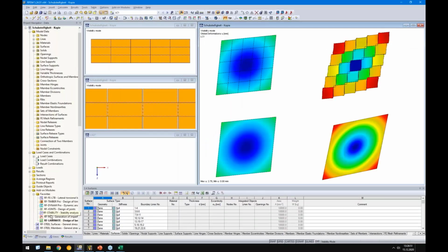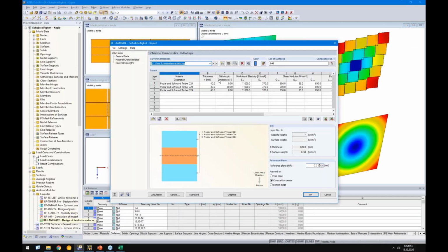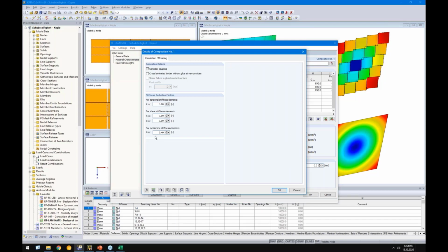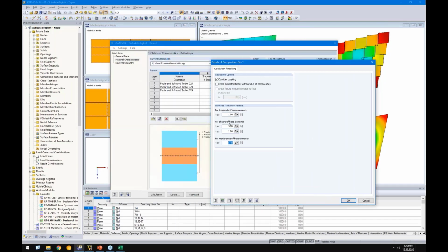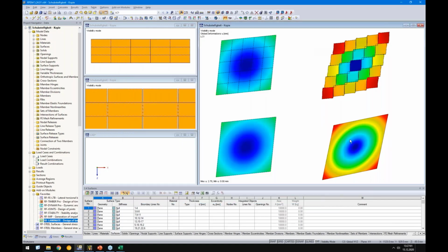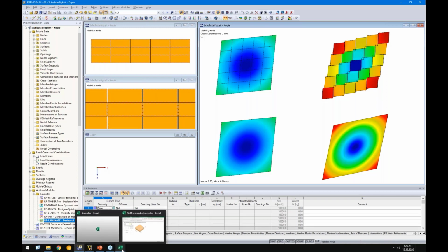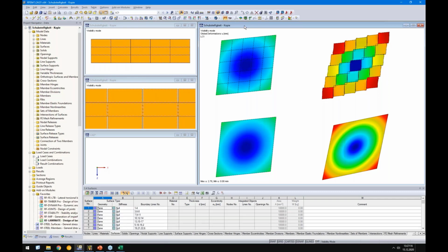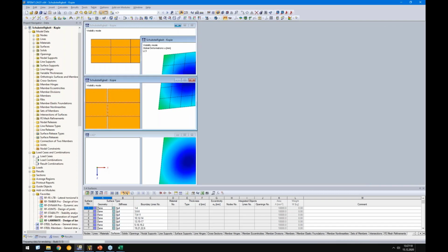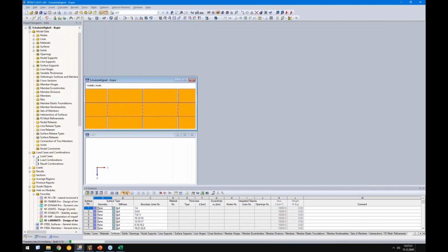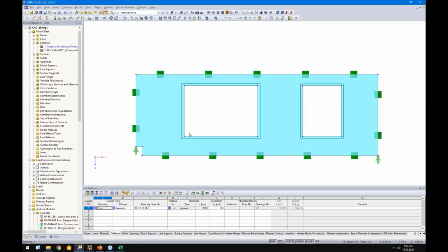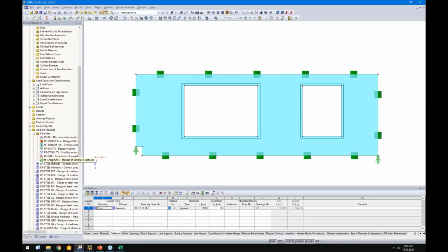And when you enter this value here in the details of the composition, as you can see here, you get exactly the same deformation as the solid elements have. So this needs to be done in case the producer does not provide us any values, but normally they do, and therefore you don't have to waste time for this. All right, so let's go back.